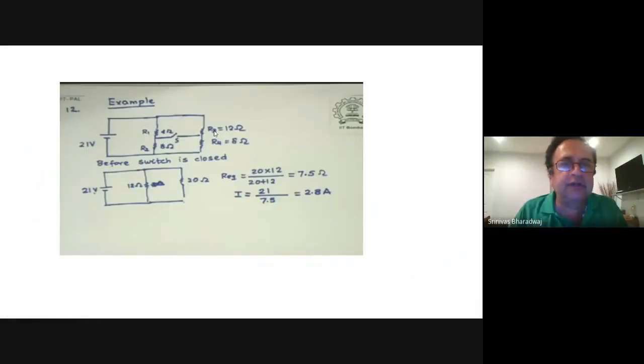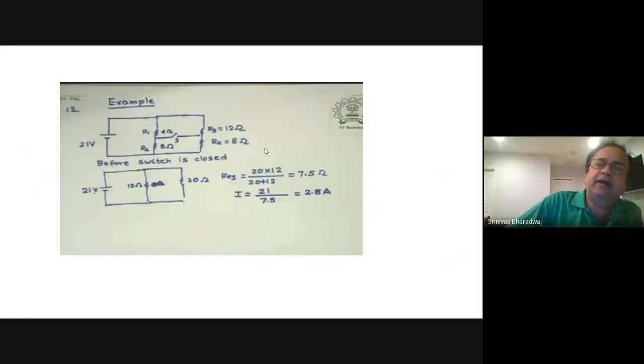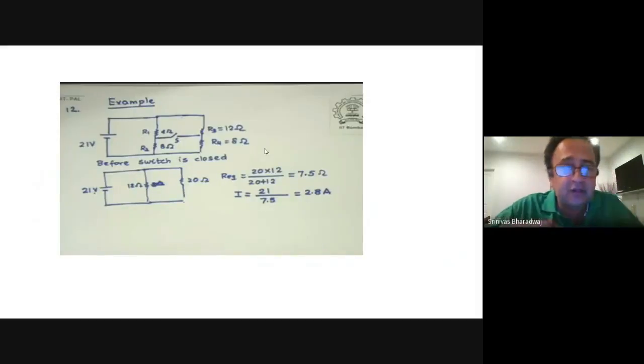Therefore, when those 2 points are connected, R1 and R3 will become 2 resistances in parallel. R2 and R4 will become 2 resistors also in parallel when the switch is connected. When the switch is not connected, it is almost as though the whole line is absent because there is no current flowing there. You might as well drop the whole line.